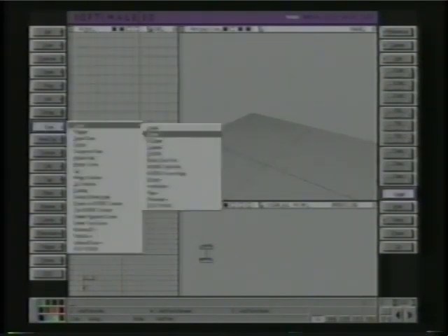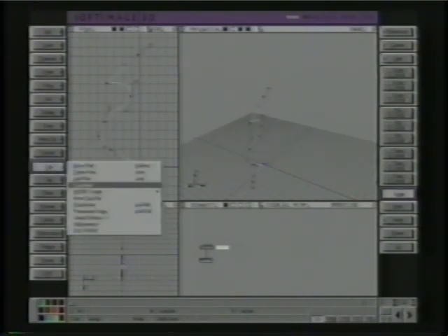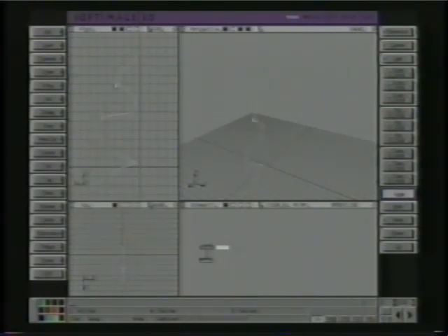First I'll talk about the Bezier format. Bezier will be familiar to you if you've used 2D illustration packages. When drawing it in Softimage, you click and drag to make handles, and click without moving to make a harder edge, even though the handles are still there. And the handles are nice because you can edit them later and have fine control with a small amount of control vertices. If you want to move them, you can use the M key or Edit, Move Point. If you use the right mouse button, you can move them without dragging the handles, like this.